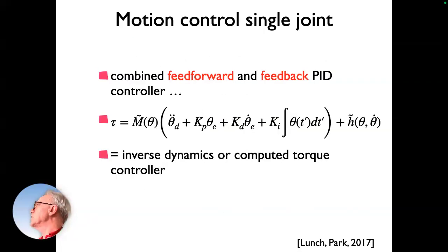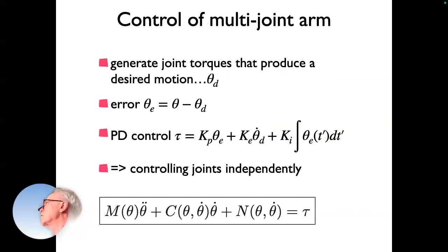So what you do in practice is you combine those two things, this feed-forward logic and the feedback logic. So here's an example. You would have a torque that is multiplied with that modeled inertial moment. You put your desired trajectory just like before, but now you also put these error terms in here. This should again have the index E, it's an error term, like the PID term, and there you have that. And so that is doing both of those things, and that's a very good form of control. It's used often like that.